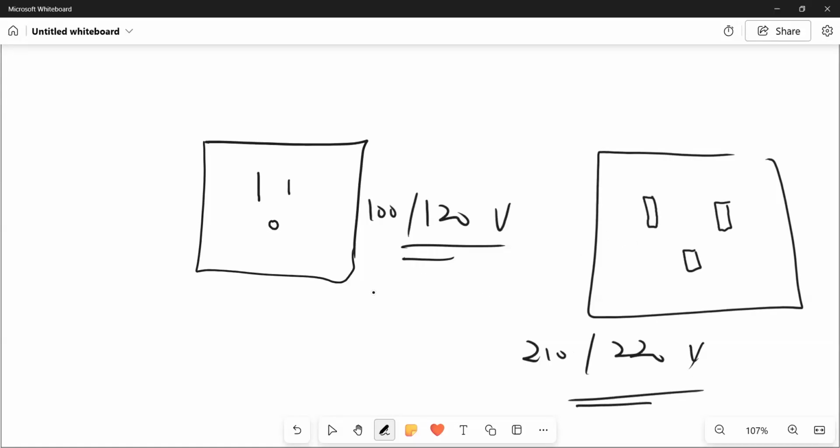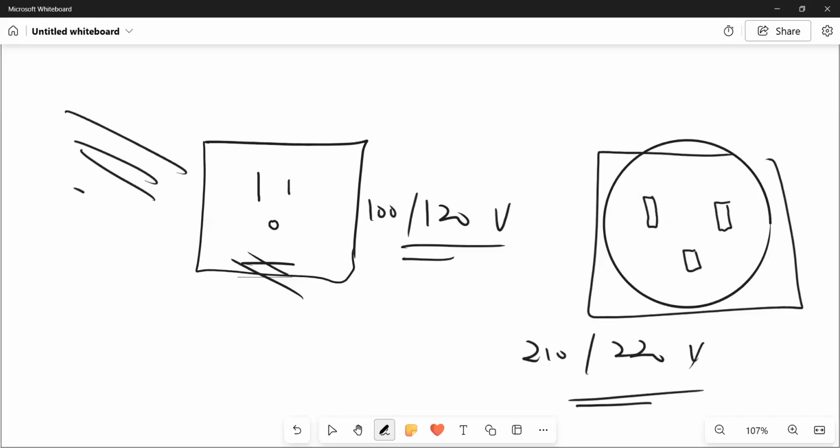So if you have a 110 plug, it can't fit in here, and if you have a 220 plug, it can't fit in the other. But we don't do that in Guyana. Guess what we do? We buy what we see. We buy the 110 thing and wire it into the 220 wire. The wire coming in there is 220, but this here is a 110 configuration, and that's why things are burning up in your house. So those are things you really want to pay attention to.